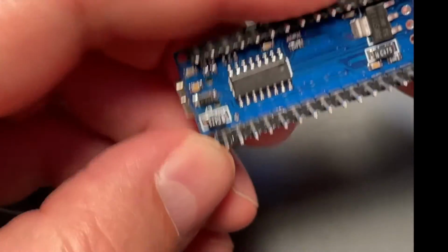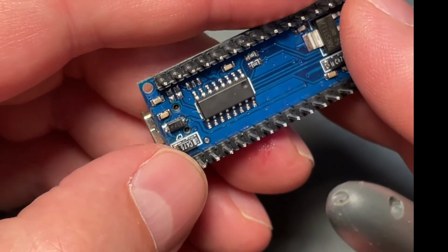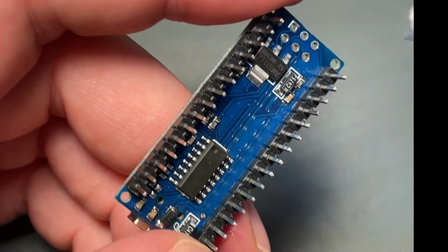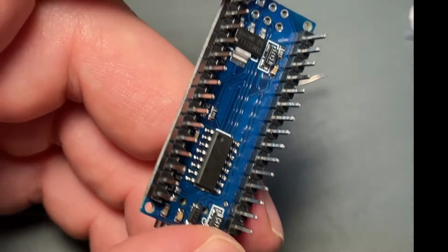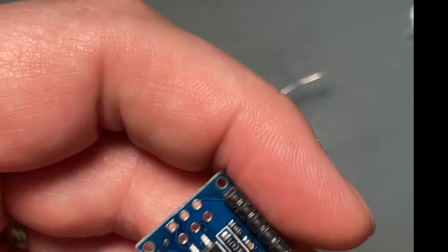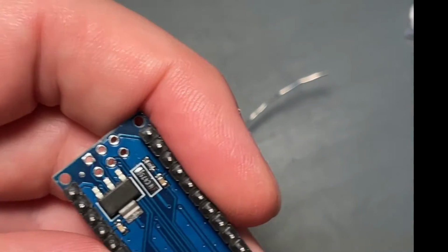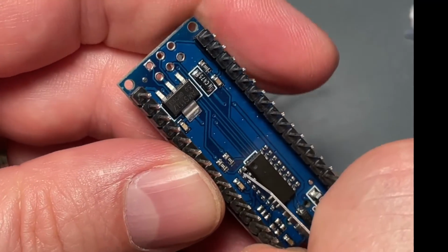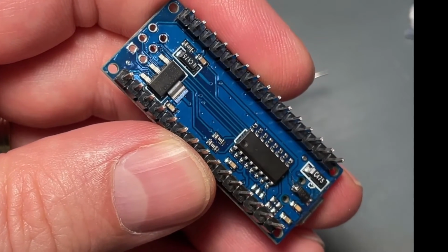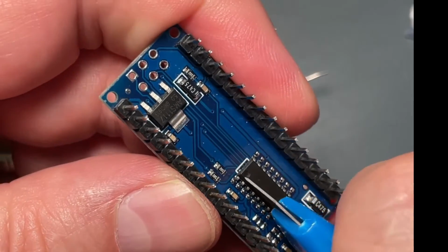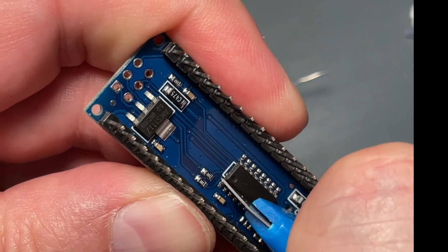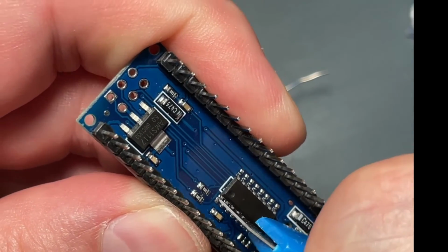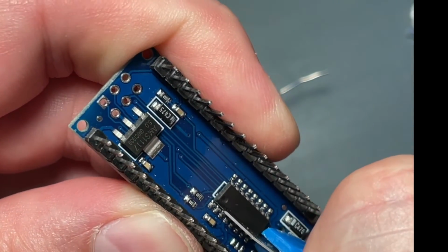Because this chip is definitely dead and causing trouble, I'm not going to care about this chip. I'm going to just try to get it out of this circuit by simply cutting it out of this PCB, hopefully without breaking the PCB itself. I've got an X-Acto knife, and now just leg after leg, or one lead at a time, I'll try to cut this chip out.